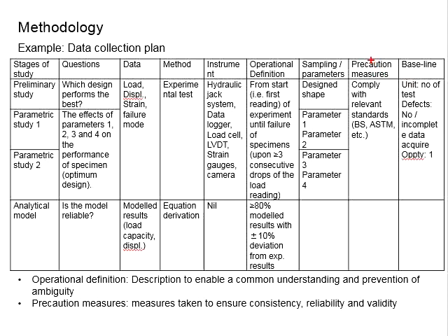And you might need to clearly work out the precautions measures. This is also important to you because you would like to conduct your experiments so that it gives you reliable results for your investigations and discussions. The best way for you to do so is finding the relevant standards regarding the testing and strictly follow the recommended procedures given by the standards. Those standards can be BS, ASTM, or others.